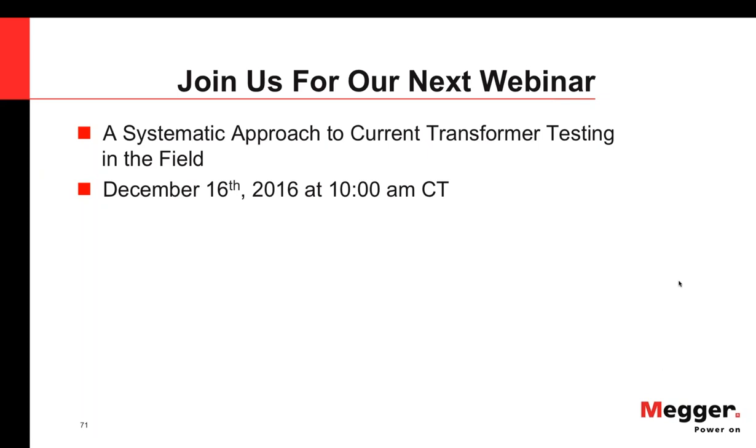So with all these different sources and DGs being put on, we're seeing a lot of power reversals occurring. As these power reversals occur, you get a lot of tap changes, and the transformers will start switching. They're rated for several thousand switches, and these can actually fail very readily. So I know there's some work being done looking at solid state tap changers.